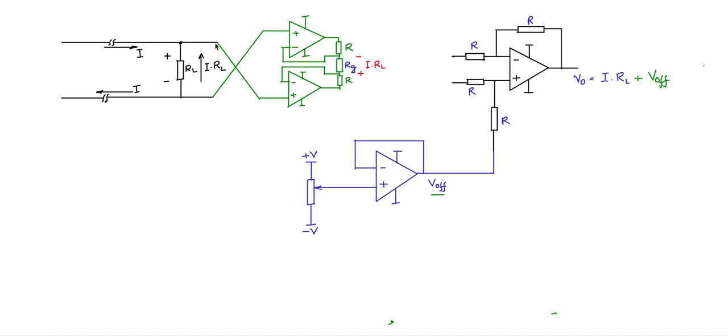The reason is that whatever this potential, virtual ground, and that potential is coming at this point, right? And whatever this potential through this virtual ground, it comes at this point. So these 2 points are the difference potential, which is exactly same as this, which is IRL. So that is IRL with the sign shown here. So which means IRL divided by RG, there is a current which is going to flow up like that. Okay, it is going to flow up like that.